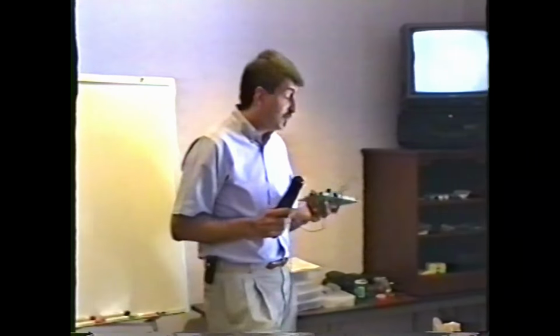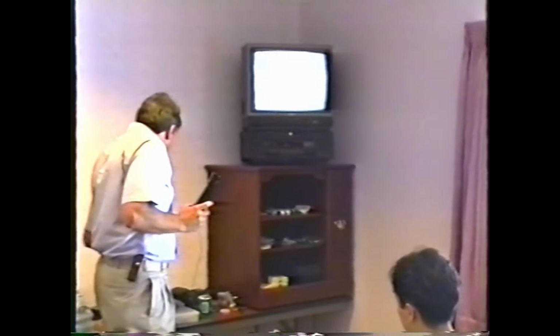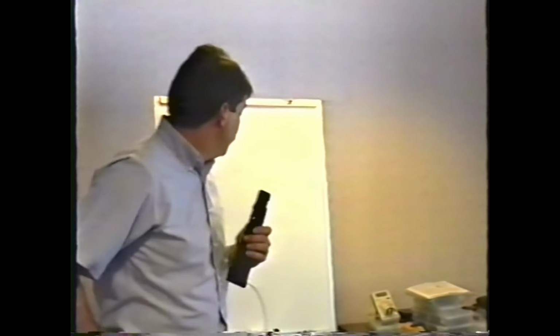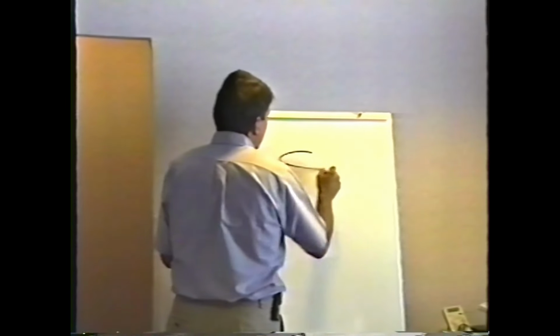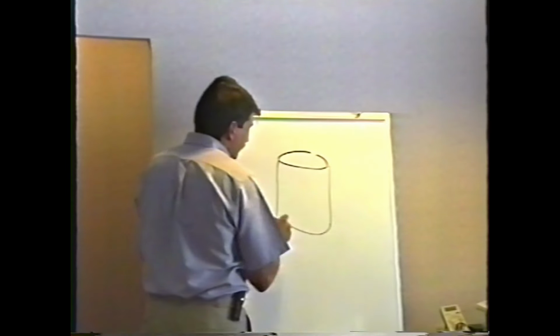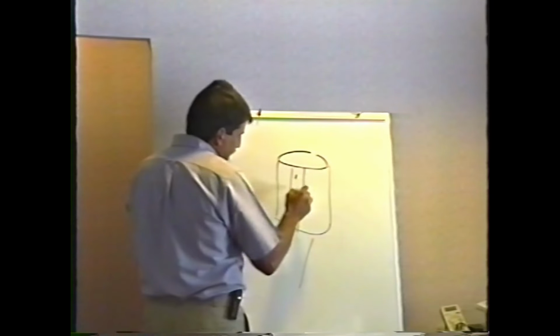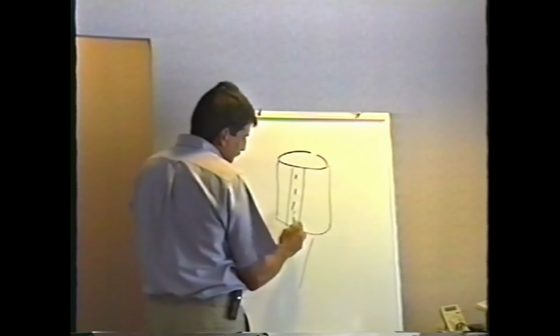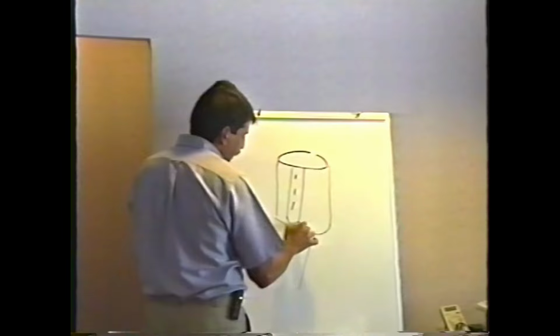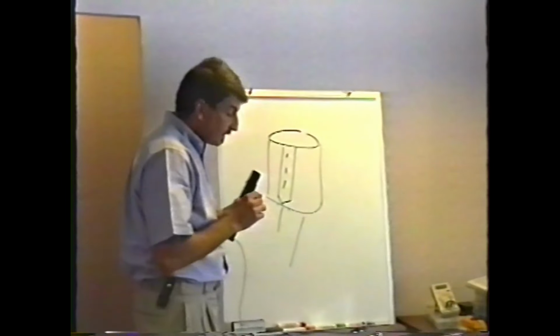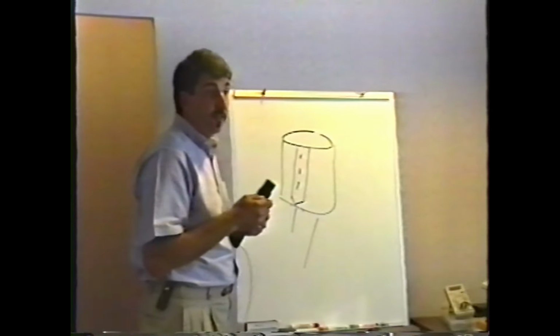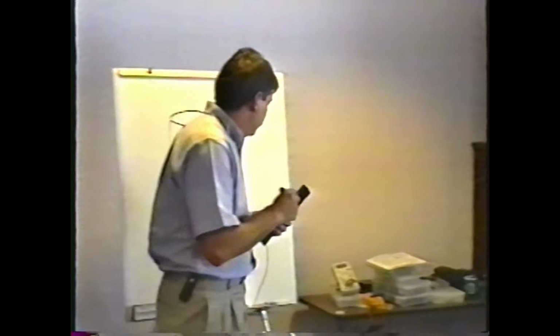Now, if you look at your capacitor, you will see that it is polarized. That is, there's a positive lead and a negative lead. And generally, the negative lead is marked on the side. You'll see like a little minus sign. Sometimes this is an arrow, like that. Okay, can you see it on your little capacitor that you have? I can show it to you. Well, here, I'll show you another one up close here.